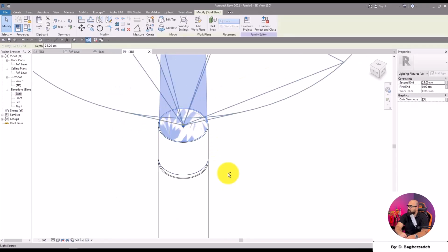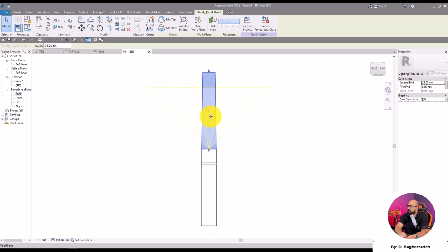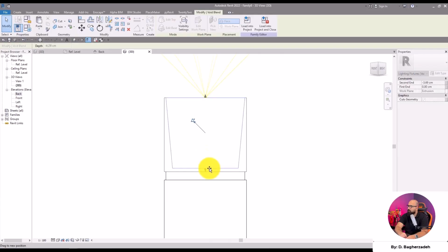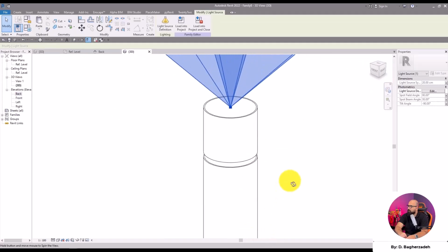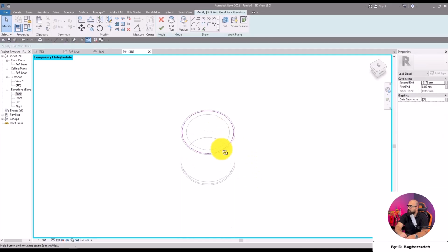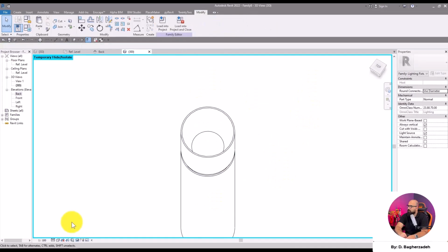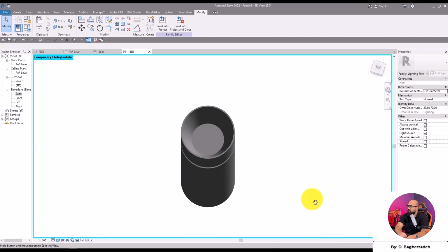Because, well, we got this void which moving upwards gets smaller and smaller. All right. So now I'm going to select this and move it down and set it here. And you can actually see this minimizing process. And yeah, now we have this cut. I guess we can even make this smaller. I mean, more precisely, we can indicate this conoidal form that we want even further. Alright, now let me set the graphic display on shaded, and this would be what we created so far.